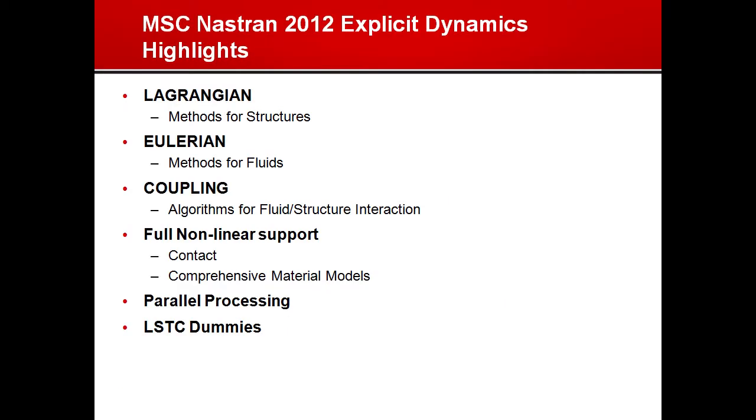So from a high level, within MSC Nastran we've got Lagrangian, typically used for structures, and Eulerian, typically used for fluids, and those fluids can have strength, which allows us to simulate structures with a fluid representation. We have some very powerful technologies that we call coupling that allow you to couple the Lagrangian and Eulerian solvers together and have an interaction between that fluid and that structure. That's a subject for a later webinar in the next month. Srinivas will talk about that a little bit. But it's very powerful technology.